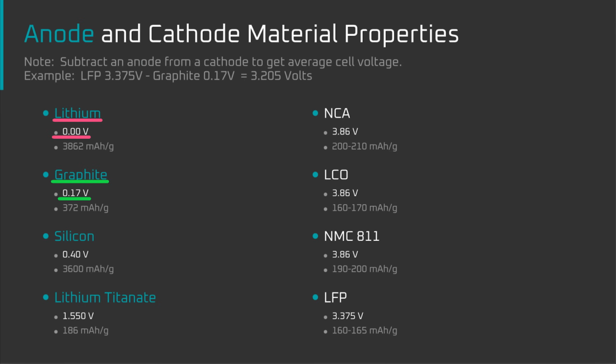That makes perfect sense to me. Because just looking at a few of the variables here, graphite has a slightly different voltage than pure lithium on the anode, and if you push the charging too high, rather than jamming that into the graphite anode, which has a slightly higher voltage, it starts plating pure lithium onto the anode. Is that correct? Yes.